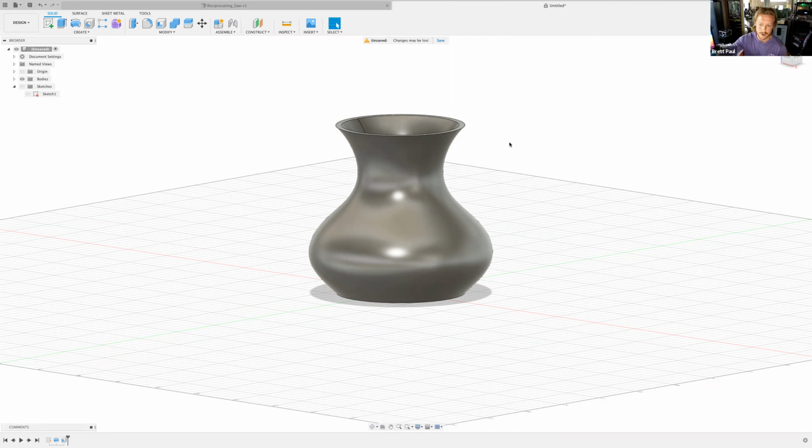I'm going to give you guys some work time. You guys can go into your, or I'll put you in the small groups again and just keep chipping away. The whole intent here was to show you how parametrics work, right? Defining, not only fully defining a sketch, but defining it in a certain way is important to going back and being able to revise that existing part and not have it change in ways that you don't want it to, which it even did for me. We kind of had to problem solve on the fly there because it wasn't defined in a particular way.